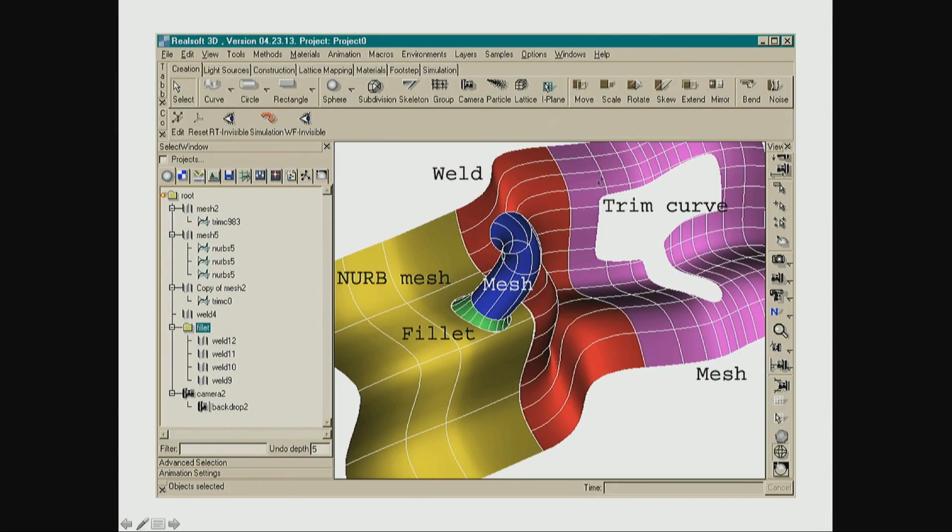And you have to accurately represent interface constraints and boundary conditions along the trim lines. So let's look at trim. Exactly what it is: here's a tensor product patch. You put a trim curve in. It's just saying there's a hole there. The underlying parameterization is the tensor product patch. This is just a mask on the visualization.